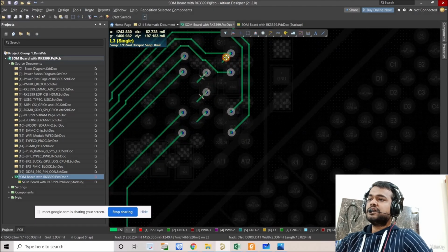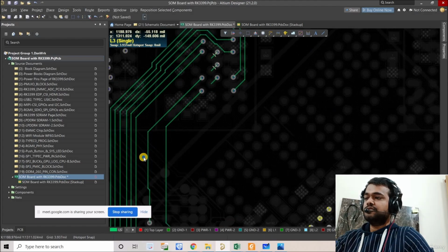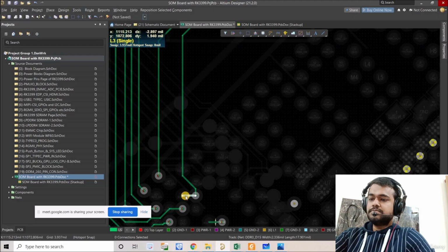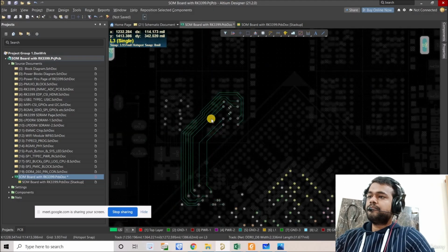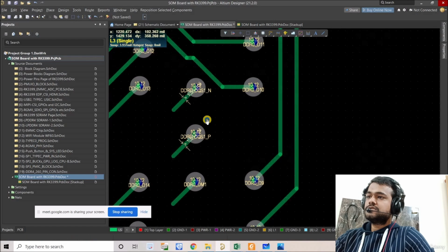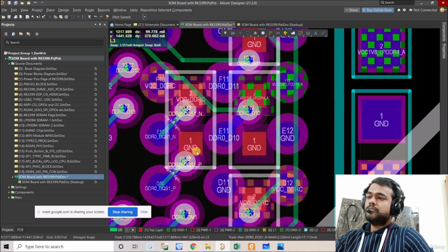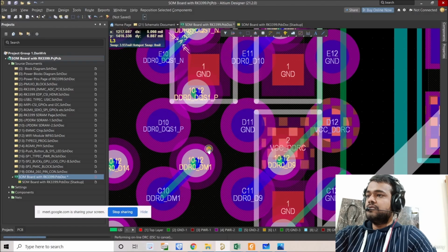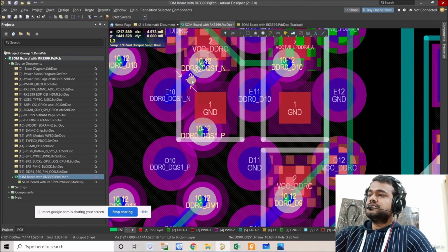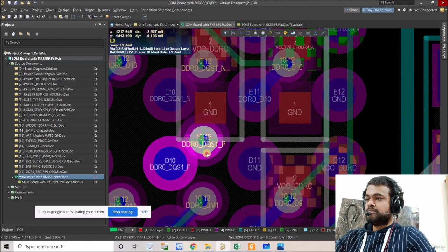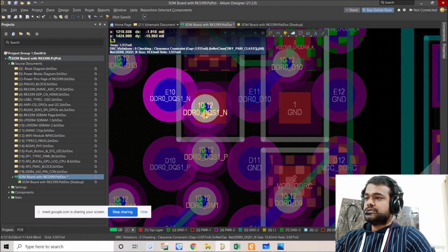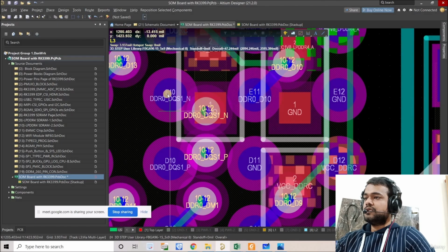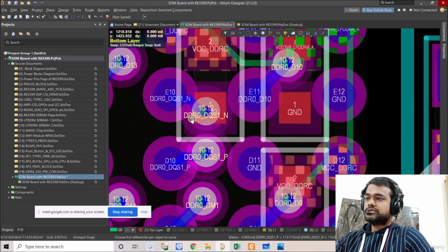Okay, now we have few differential connections and one differential connection and another one. So for differential we'll follow the same way. How to do it? So firstly remove the stubs. Okay, so for this, okay, firstly remove all these connections, which is kind of creating some width related issues. Then place those close here. Now select the differential net, sorry, differential routing and connect those, right?